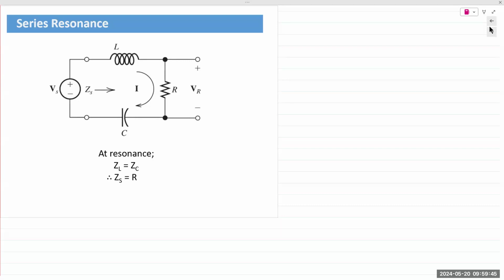And so for that reason, that voltage may appear larger than the source, just in magnitude, again, because the capacitor impedance points straight down. This is a very important concept for the last topic of 201, which is AC power. AC power is all about energy transfer between inductors and capacitors. This is a very important concept there too.